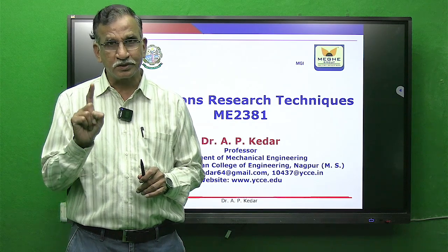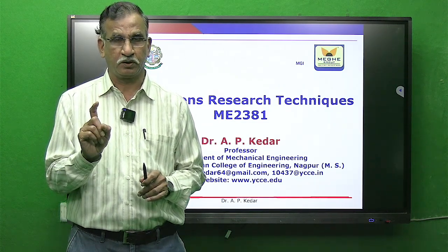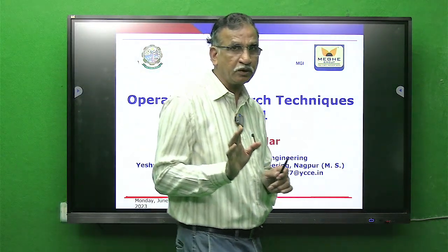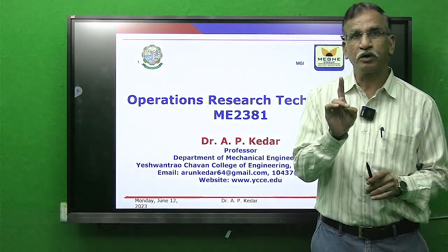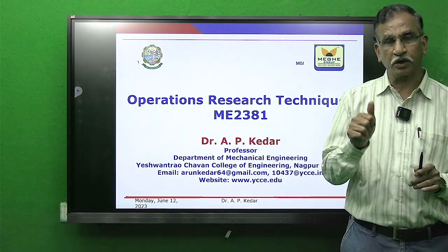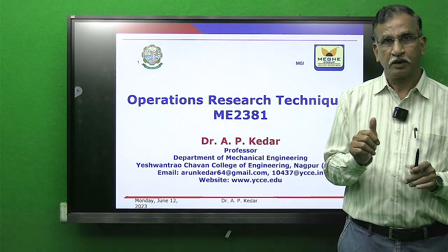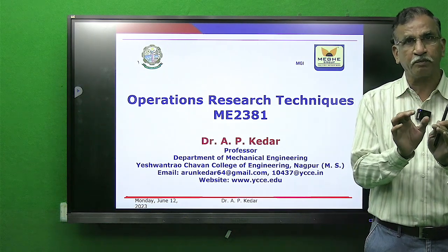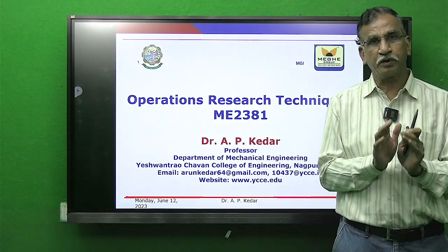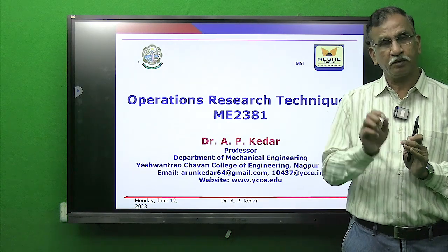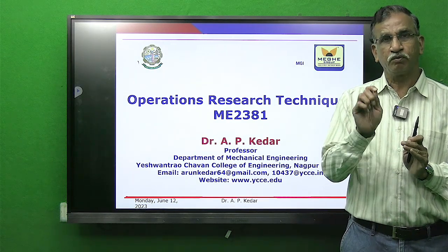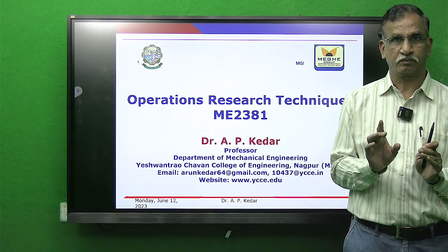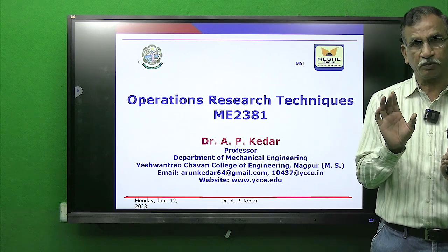This calculation is necessary for PERT activity time. When it is a critical path method network, you will be provided with only one time estimate. There is no need to calculate time estimates separately. Remember one thing, the methodology till finding the critical path is the same for PERT as well as CPM. In both network analyses, we have to carry out forward pass and backward pass calculations. Be sure that you remember this.